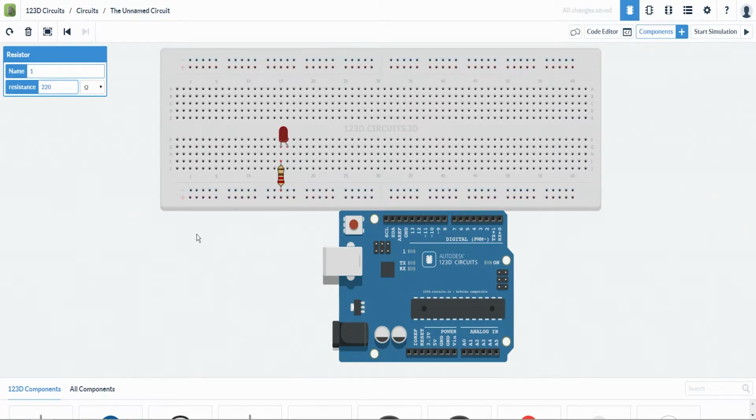So now we're going to start wiring up. Basically, we're going to get our ground power and attach it to the ground rail of the breadboard. Then we're going to pick a random digital pin, so let's pick 8. We're going to set terminal 8 as an output. It's either digital output or digital input, and we're going to set it to the power side of the LED.